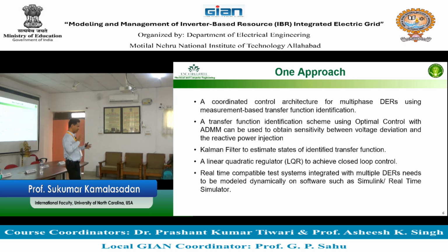Because of the electric grid topic, we are still on that. So that's device level control, local level control. The next level, we call it secondary level control. What secondary level control does is, the area will provide a signal to this local control and say, hey, this is the signal that we want. To derive that signal, you need some control action, some controller. What are the signals that are important from the area which go to the local device? Voltage and frequency. These are the signals required to go to the local controller. So that's why we call it the secondary level controller.